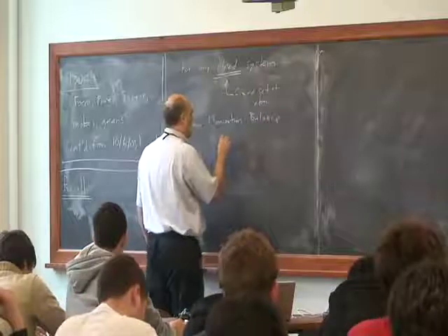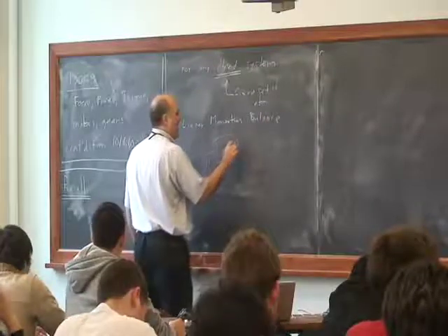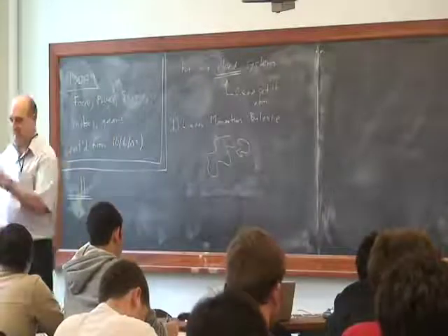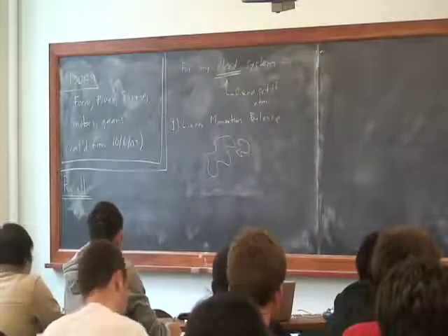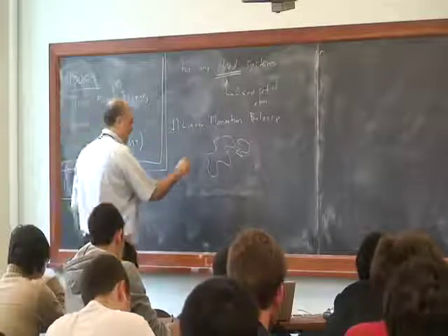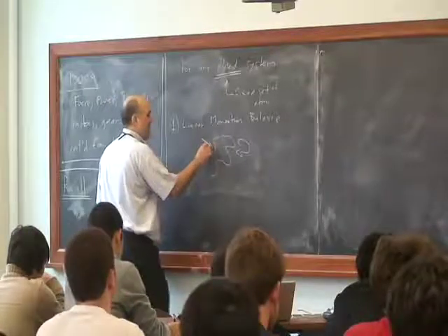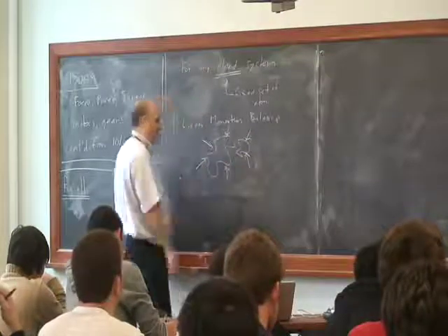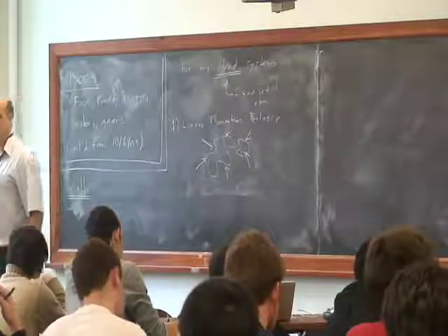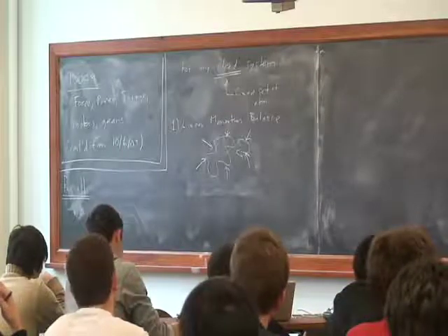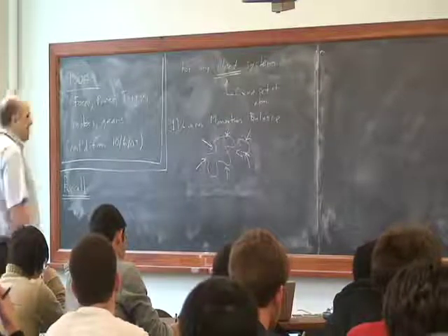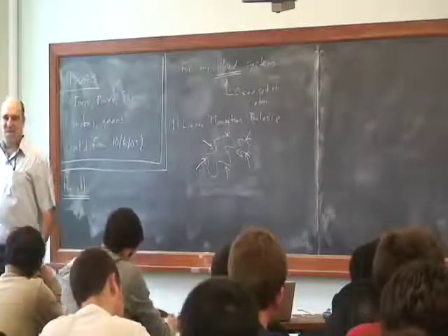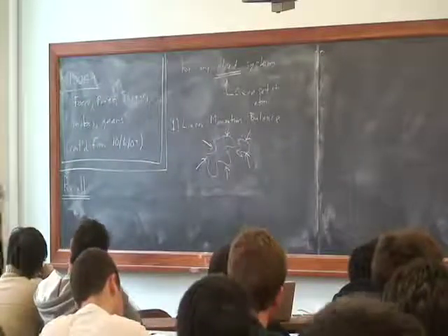And it says that if you look at the system, no matter how complicated it is, in fact, it doesn't even have to be parts which are touching each other. The system could be any collection of material you want to pay attention to. If you look at the external forces acting on this system, and they show in a free body diagram, and this thing is called a free body diagram because the word body in this context means system, and the system could have various parts. It's still called a, quote, body, even if it's many objects.